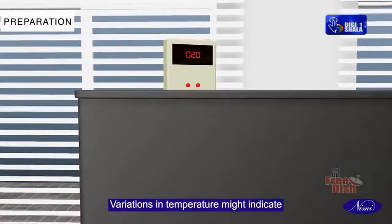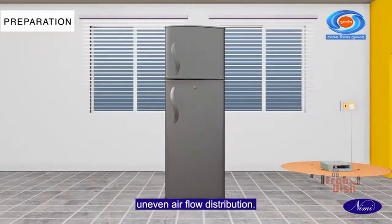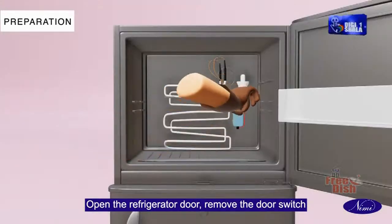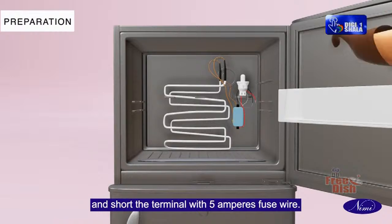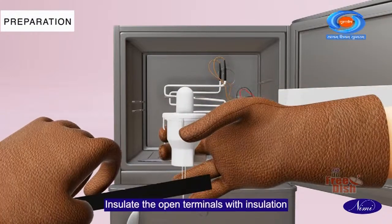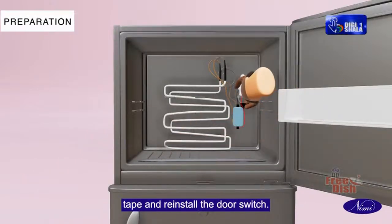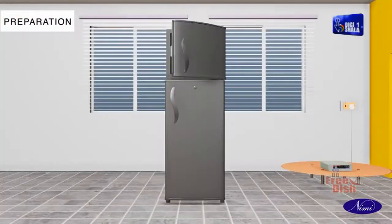Variations in temperature might indicate uneven airflow distribution. Open the refrigerator door, remove the door switch, and short the terminal with 5 amperes fuse wire. Insulate the open terminals with insulation tape and reinstall the door switch. This will make the evaporator fan run continuously.